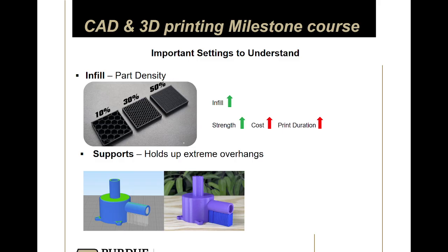Increasing that infill percentage will give you a little bit more strength, but obviously more material and time. But like I said earlier, I recommend you increase your perimeters before you increase your infill because it's typically faster and it'll still be stronger and lighter. So I recommend that before anything.